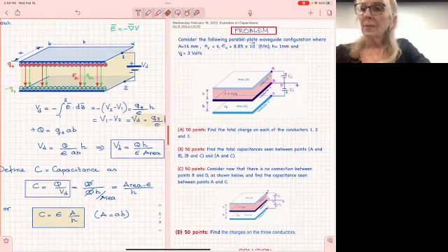And because the electrons do that constantly, and because mu sub r is very high, they have a lot of loss, from scattering and other things. So the loss inside the magnetic materials is very high. That's why we don't put them in. They're very expensive too, and very difficult to make. So we go for dielectrics. Okay, so that's one question for you.